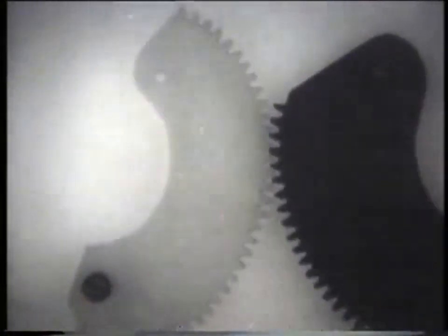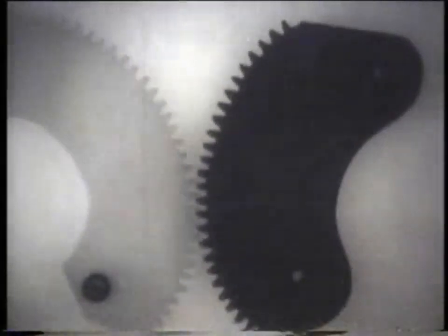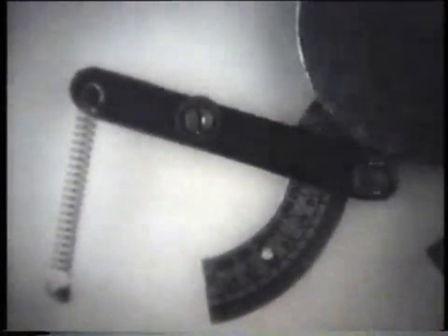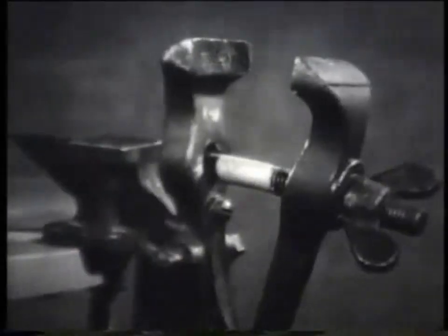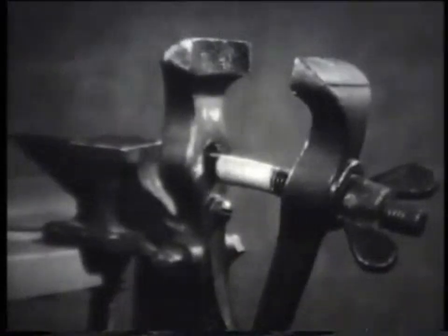Movement in space can also be transmitted using a worm mechanism, which consists of a worm and a worm wheel. In some designs, non-circular gears are used. In these wheels, the teeth are cut along the surface of a profile made along a curve other than a circle. In a cam mechanism, the cam, when moving, drives a swinging or translationally moving pusher. The links of the screw mechanisms are a nut and a screw.